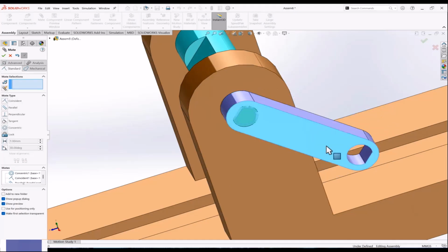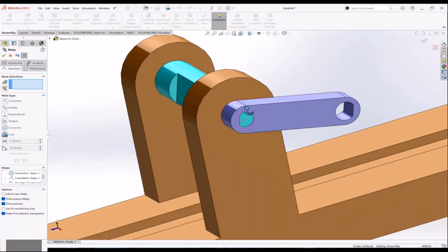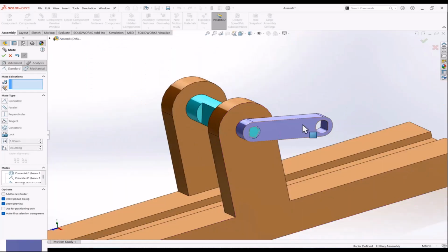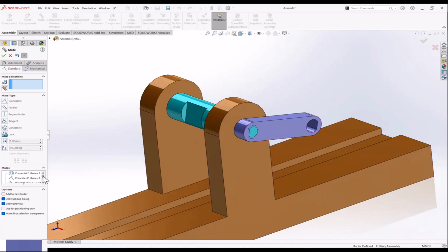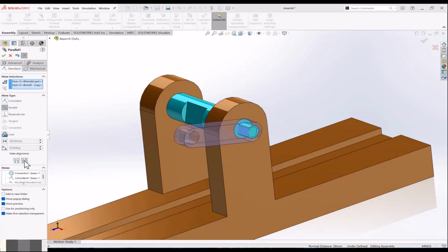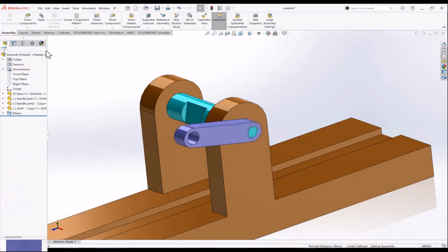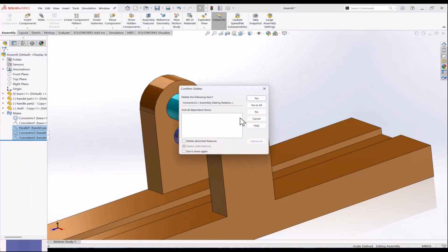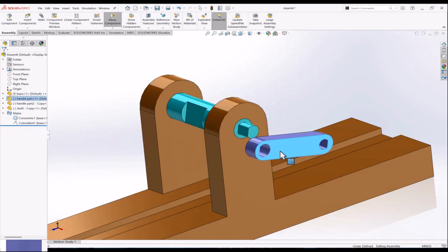Now we'll say this face will be stopping at this face. That handle arranged. Next, I think that flipped the wrong side. So the face is actually smaller now. So let me delete the relations and then arrange it properly first. So parallel is what? Between this face.